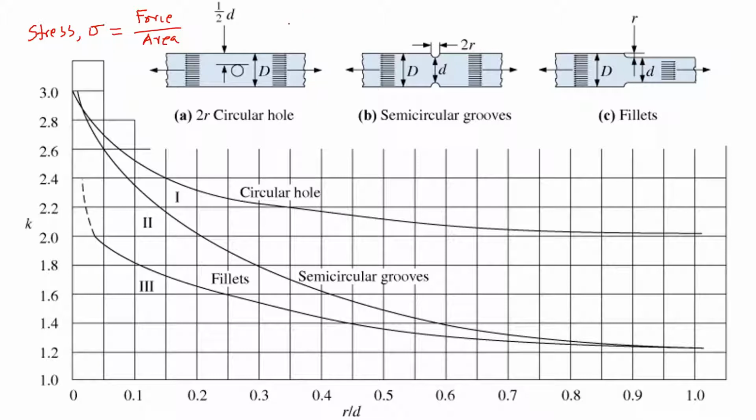For example, if you have a welded piece like this, you may think it is the same material, but the stress on this corner will concentrate more than in any of the other areas. As you can see, it will fail here much quicker. If this corner is very sharp, then the stress can multiply all the way up to 3 times, as you can see, the K factor.